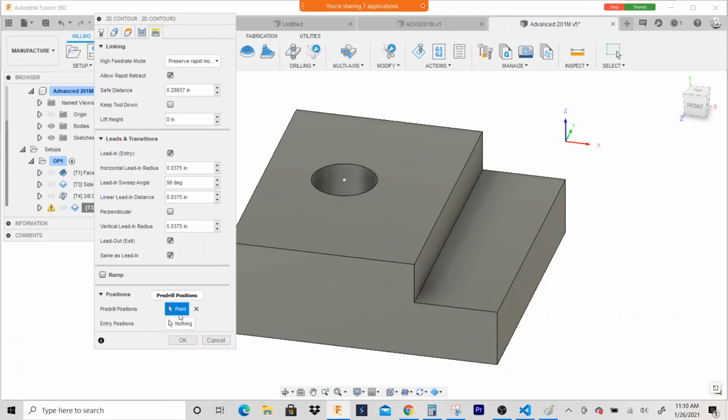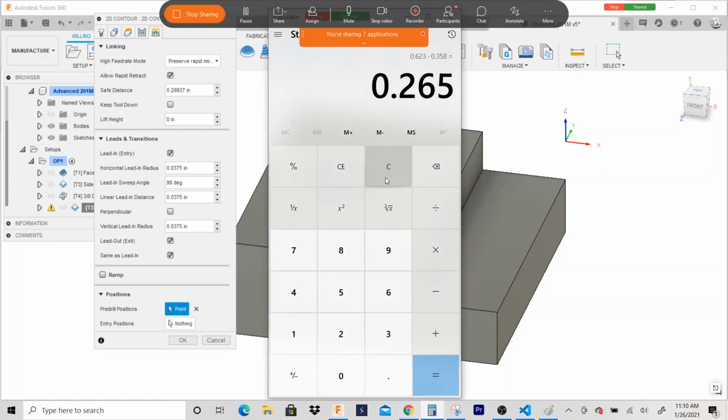So if you go to the link, I did pre-drill, but the hole size is 0.42. Okay, so if I pull up a calculator right here, our hole size is 0.42. Now our end mill is 3/8. So if I subtract that, we only have 45 thousandths of material, but that's diameter value per side of the part. We'll take that, divide by 2. We only have 22.5 thousandths of room, because if you drop a 3/8 end mill in the middle of that hole, you only have 22.5 per side distance to go.